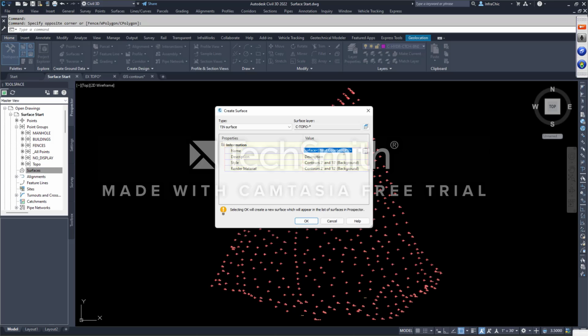If I click in the box once, it will highlight it. I'm going to start off, this is an existing surface. I'm going to start off with EX because I want to make sure I know it's existing. You might have X. Every company has some type of standard, some don't. Your choice then, EX for me. Survey, topo, ground, point surface, I don't know. I'm going to go with survey. Existing survey. Simple, okay? I could add the description. Now I can get wordy. This is points from session 1, surfaces, survey. Okay, I can get really wordy if I really want to.